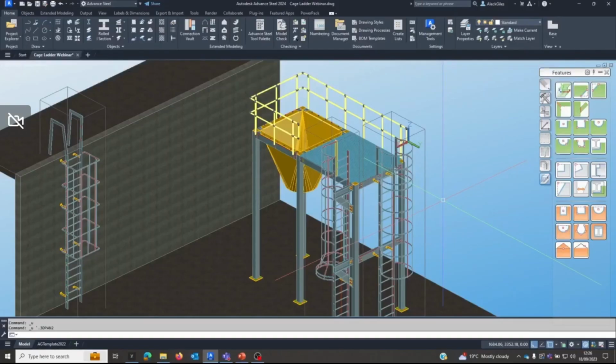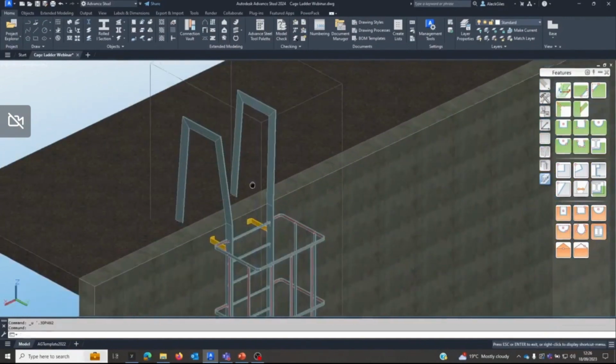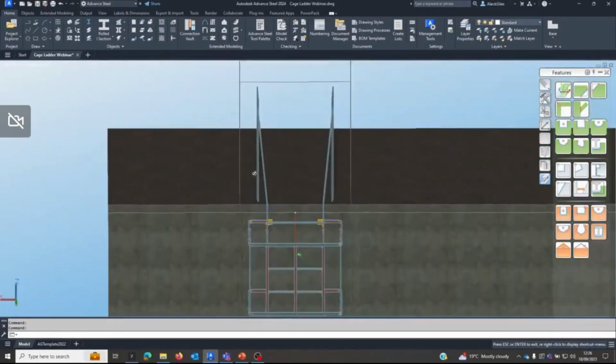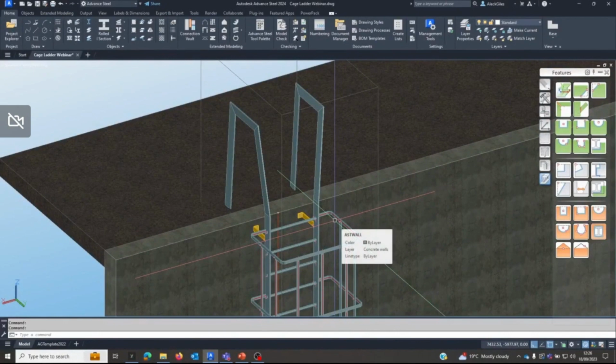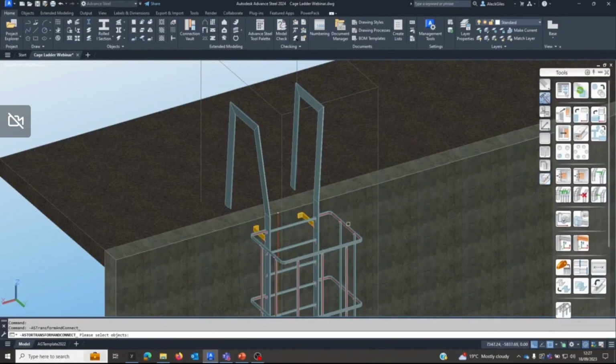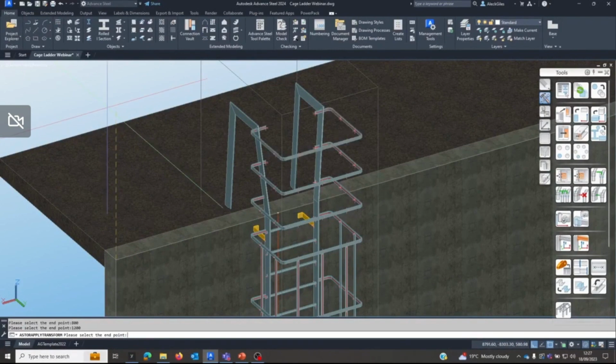So what happens when you don't have a parallel exit? Well, on our first ladder we got this exit type 4, which is a tapering exit. So let's try and work out what happens there. Well, it's the same idea. You've got to copy some braces, make sure you've got braces in all the positions, then it's just simply extend the bands. So I'm going to copy these braces up. Just the top line will do. I'll guess some distances, so maybe something like 400, 800 and 1200. That'll do.